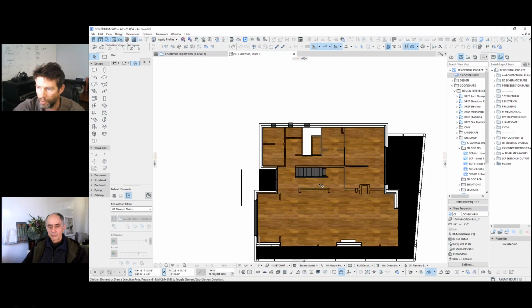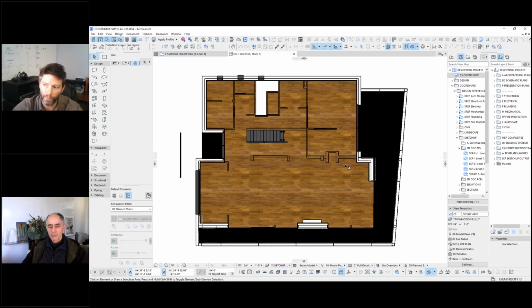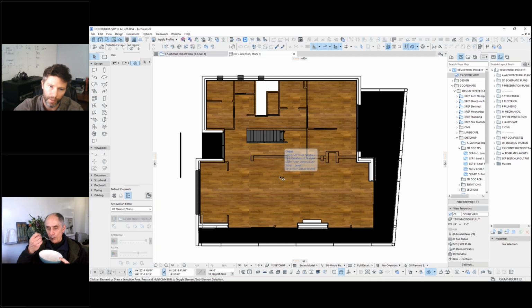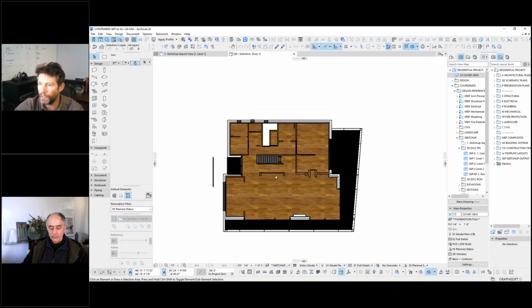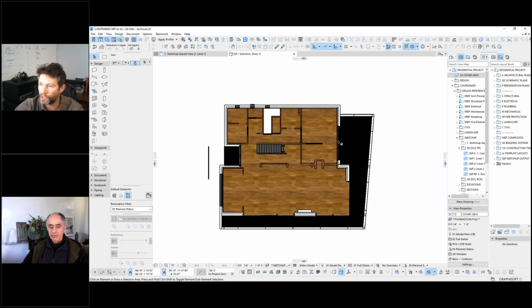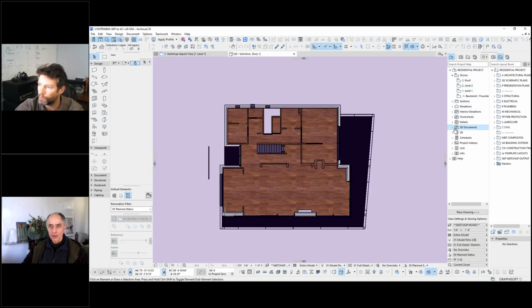been a little annoying. But anyway, in order to generate a 2D version of this top view, which I had activated just by clicking on this look perpendicular to and then clicking on the main surface. From here, I would then save off a 3D document of this particular view. So we would go in, we'd go to our 3D documents or click outside of our crop zone, but we have our 3D documents here, and we would go do a new 3D document from the 3D, noting specifically where